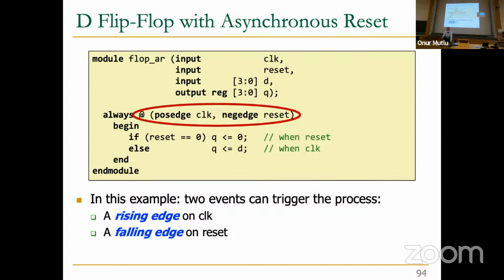That's also called the rising edge of the clock. And when the reset signal goes from 1 to 0, that's called the negative edge or falling edge. So I'm just giving you another terminology over here. Pos edge means rising edge, neg edge means falling edge also. The rising is 0 to 1, falling is 1 to 0. Any of these two events can trigger these two assignments, potential assignments, I should say.